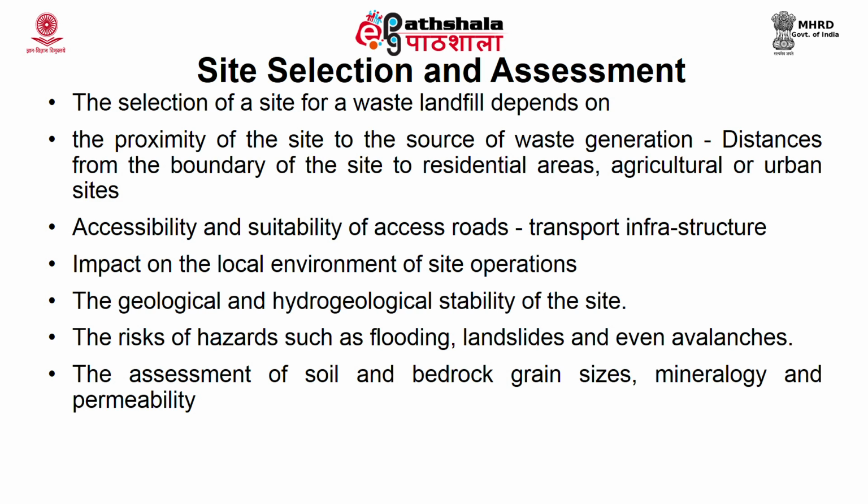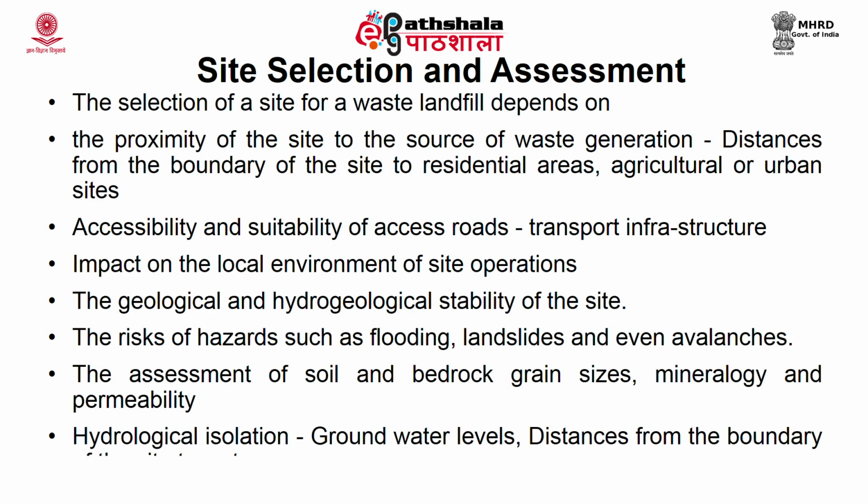If you understand all these things, it will help you to design the landfill in such a way that it does not cause any pollution. Then hydrological isolation. Hydrological isolation means it should be away from water bodies, be it groundwater or surface water. The site should be isolated from these water bodies.